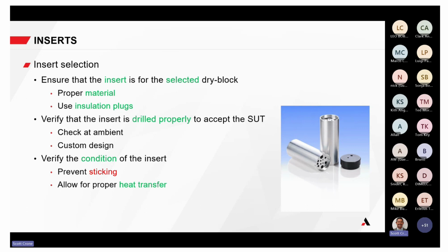And you want to verify the condition of the insert. So you want to verify it's clean and it's not dented or scratched to prevent sticking in the well and sticking of the sensor under test. And it will also allow for proper heat transfer. So if you've got a very dirty insert, it's not going to work out well.